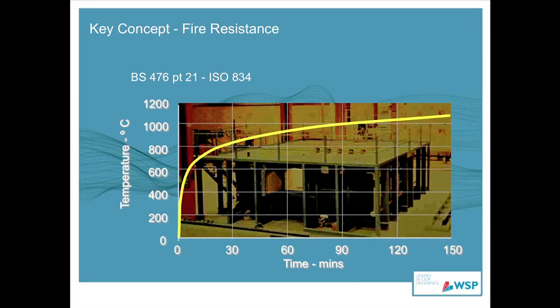And obviously that's underpinned by the fire resistance test. And obviously we've already heard what that test actually involves. One of the major drawbacks in understanding what happens to real structures in real fires is that the test can only test elements of structure. Most of those elements tend to be unrestrained, whereas in real structures there is a lot of restraint to all the main members in the load resistance system.